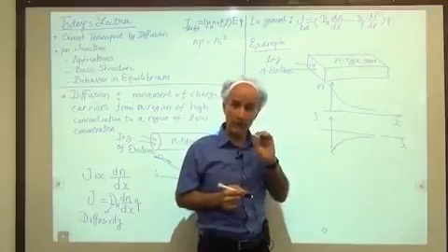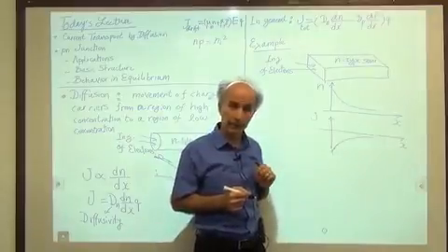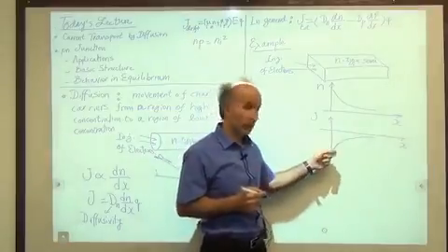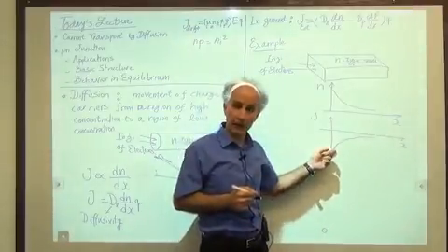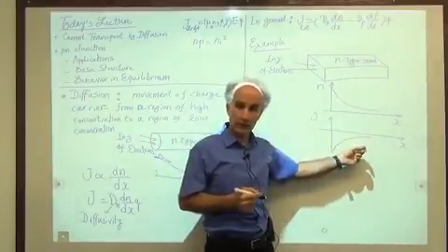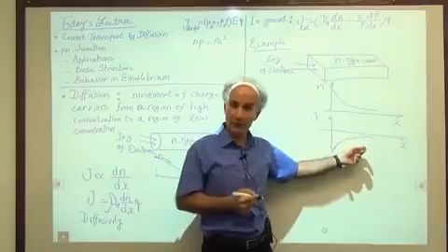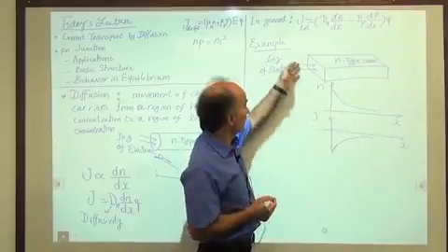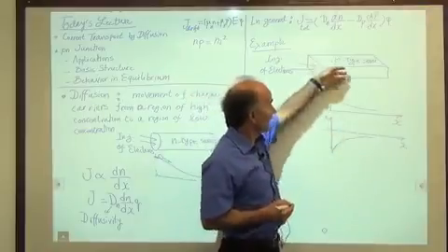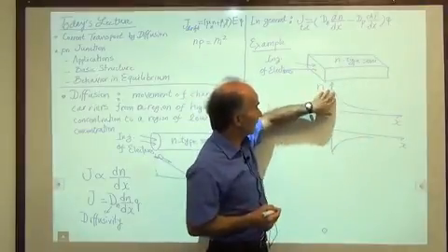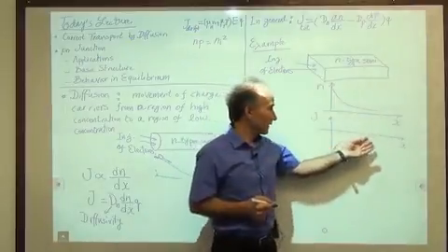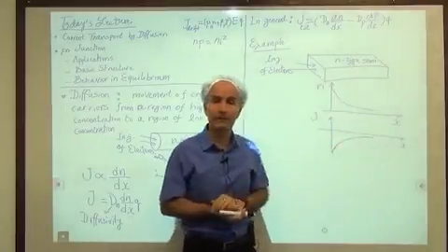And again, it's only consisting of electrons. So something strange is happening here. We had lots of electrons here carrying the current, but by the time we got here, we don't have that many electrons left. What happened to those electrons? When we injected these electrons into here, and they started propagating because of the concentration difference, they were rolling down this hill. Why are they disappearing as we go here?